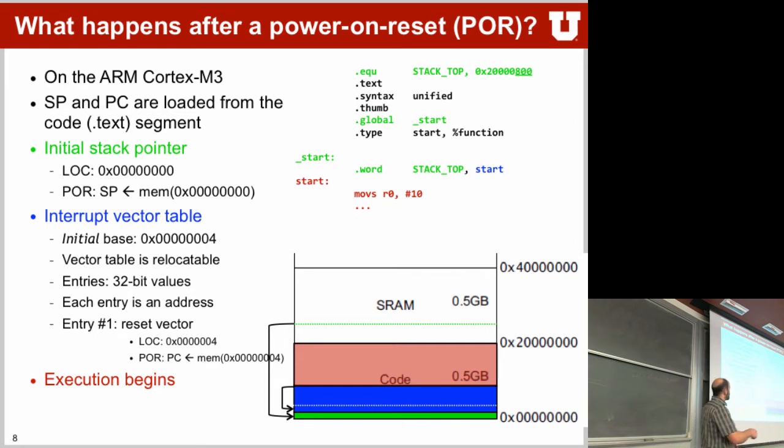So again, you now can see down here in this little assembly code, we have the stack top set to our stack memory address, right? As I said, it grows down, not up. So we have 800 hexadecimal bytes of stack. And then we tell it that global is the start address, and this will be put at the very beginning of your application, so address 0 and address 4, and then the rest is all the text area that will start getting executed.